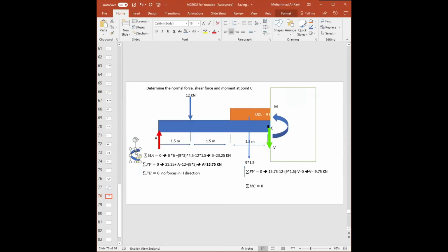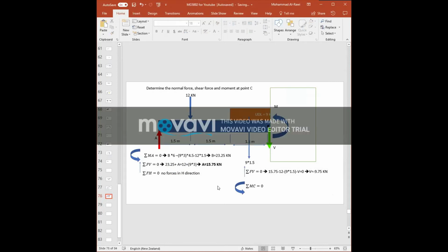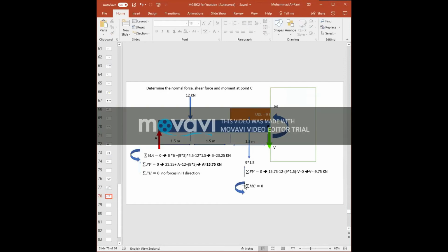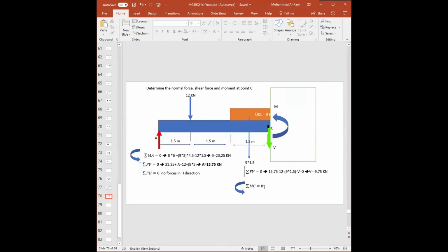Now, I'll assume again that the positive direction is counterclockwise. Today, I always, like maybe in the last 3 weeks, assumed clockwise. Today, I decided to use counterclockwise just to show you the difference and how it works when we solve it in a different direction, just as a try. All right, so for this question, counterclockwise, take moments around C. Remember, when we say around C, this moment will not be canceled. So please be aware, the moments will be added. The only thing canceled at that point is the effect of the shear force V, which will go away.